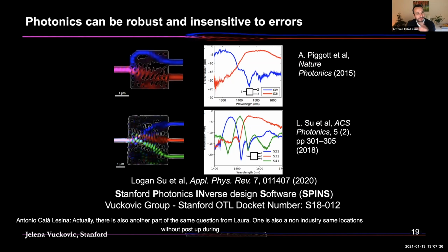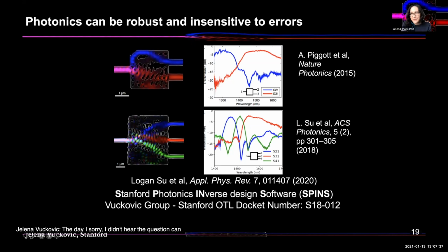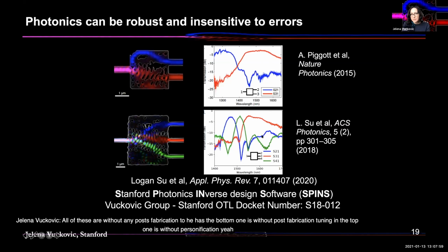Actually, there is also another part of the same question from Orad. Do all of the resonances also line up in the same locations without post-fabrication tuning? In these WDM devices or in the resonant devices? Okay, this picture. Yes, all of these are without any post-fabrication tuning. The bottom one is without post-fabrication tuning and the top one is without post-fabrication tuning. So it was just measured directly.